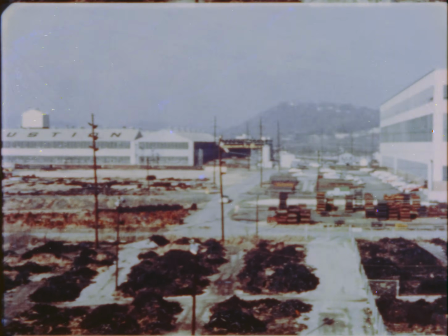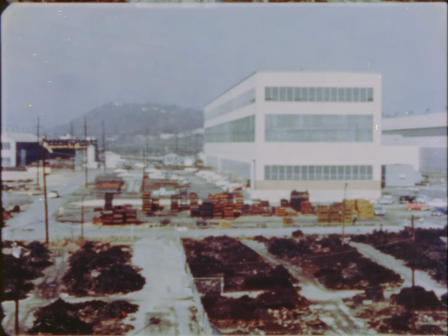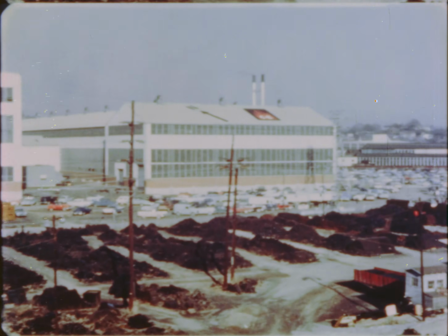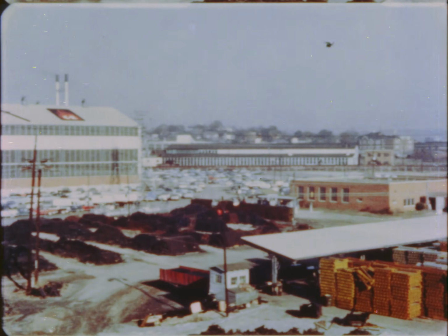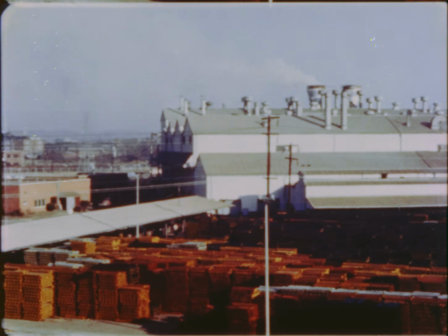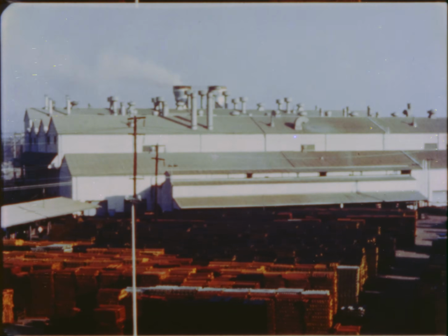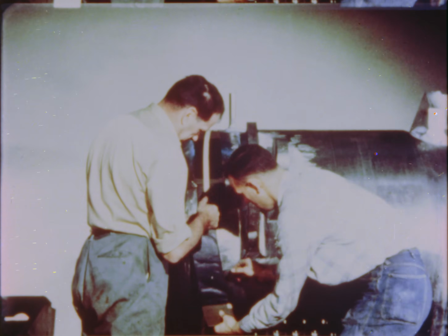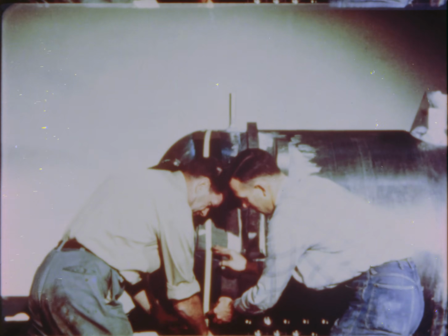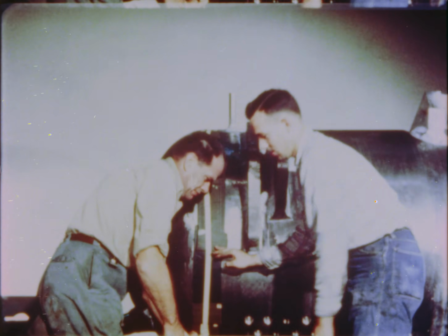At this Tennessee plant, where pressure vessels, boiler tubes, and other components of conventional and nuclear power systems are fabricated, radioisotope units have taken over a large portion of the radiographic work. To determine the integrity of girth seam welds on a boiler such as this, film is attached to the area to be inspected.